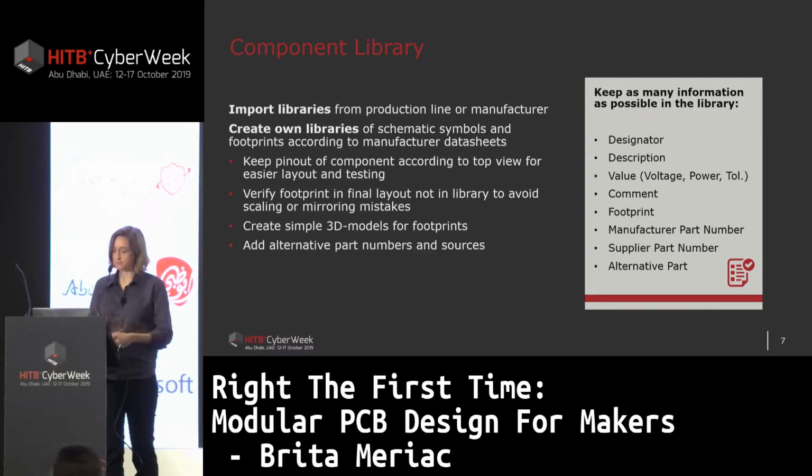Some tips for the schematic symbols: keep the pinout according to the top view of the component. It will help you a lot afterwards for testing and debugging. The footprint: you definitely verify the sizes in your library view, but it's very good advice to actually check the size in the final layout.